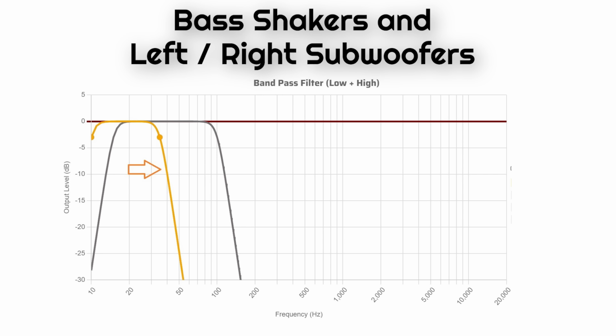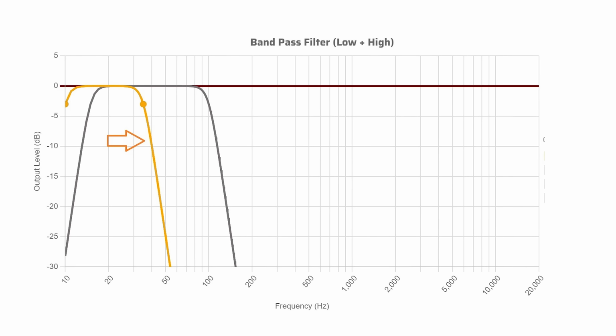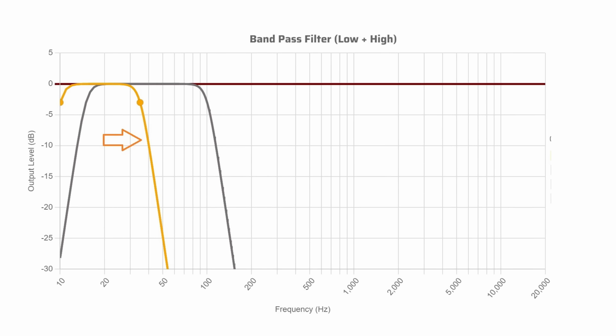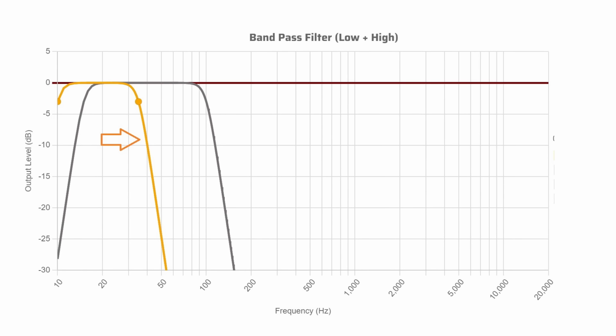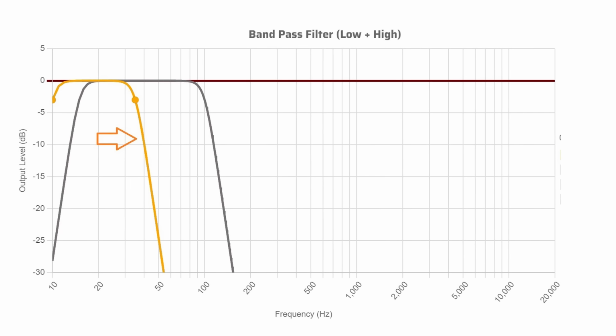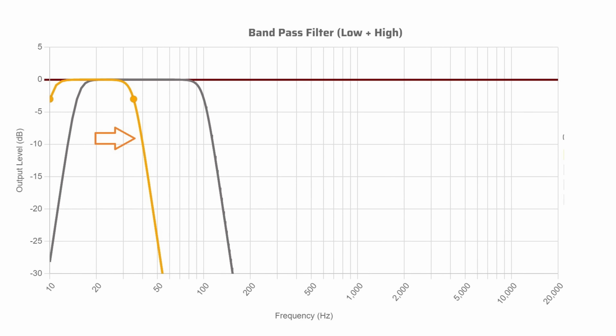Bass shakers or butt kickers can add a lot of intensity to your home theater experience. Here, we have chosen a frequency range of 10 to 35 Hz. This applies power to the useful range of the shakers and also eliminates annoying audible output above 35 Hz.